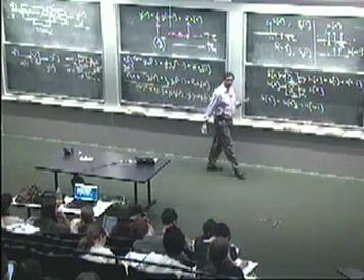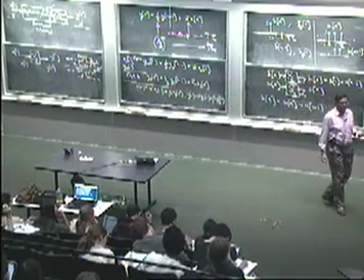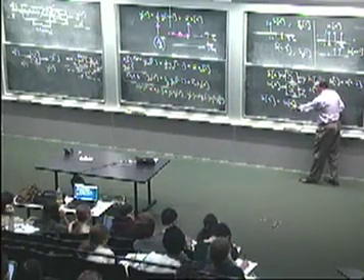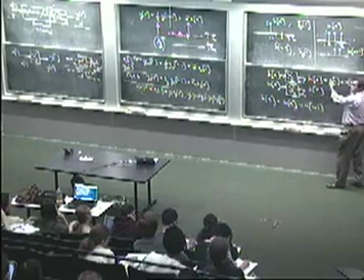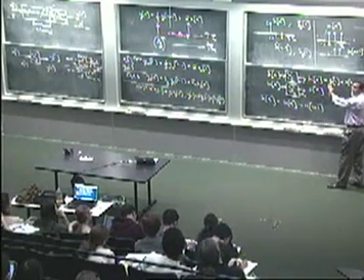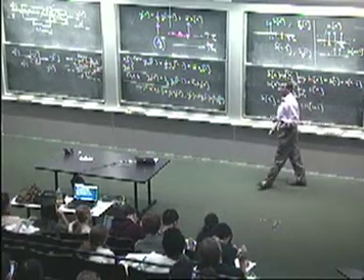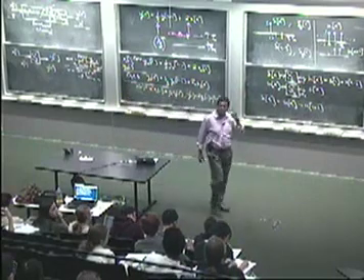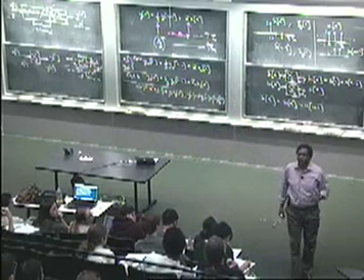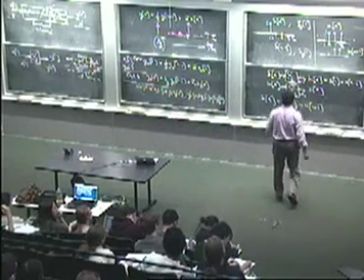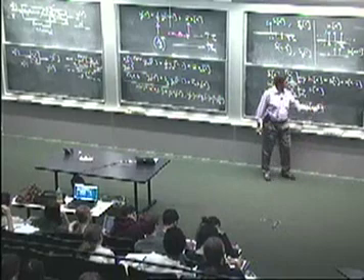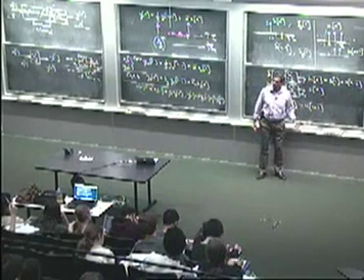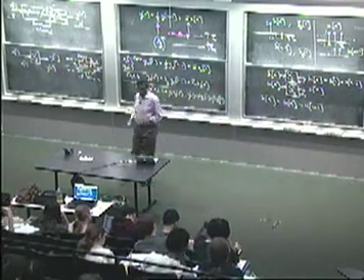The superposition idea was part of the definition of linearity, right? Because the system is linear, if the input is a superposition of two inputs for which you know the response, then the output is the corresponding superposition of the responses. That seems like I've only used superposition there. Have I actually used time invariance as well? Yeah? Sorry? I've used it in concluding that if I put in u of n minus 1, the response is S of n minus 1. Okay, so I've used time invariance as well as linearity here to come up with the statement. Okay, good.